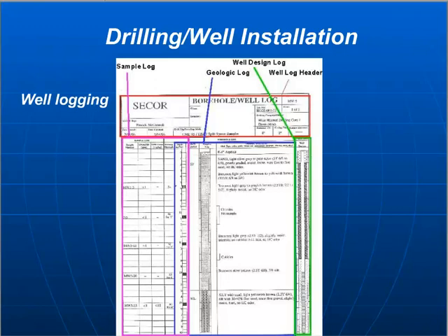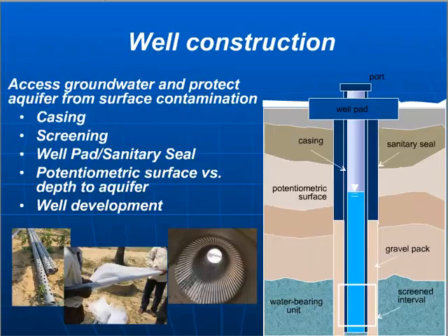It seems that I'm working with a couple chapters right now, so maybe that's why it's fresher in my mind, where they have a lot of sediment in their wells, and they don't know why. They're not sure if it's just a problem with the aquifer itself. They don't know if maybe the right screen was not installed, and so there's sediment getting through.